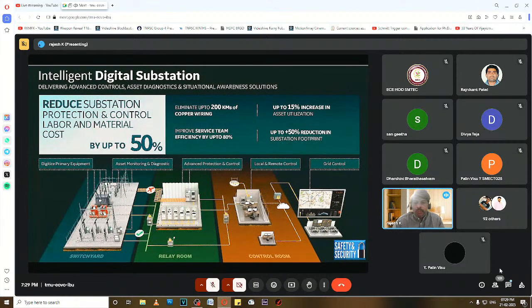For example, if you have a voltage and a current, they normally come from the voltage transformer or current transformer, which is essentially an electromagnetic winding with coupling. We step down the voltage in a voltage transformer and step down the current in a current transformer. This works on the principle of induced EMF and flux linkage to the cores. Then it is wired all the way to your panels or control room. So you will have hundreds or thousands of wires running between the station and your control room, to the protection, control or measurement devices.